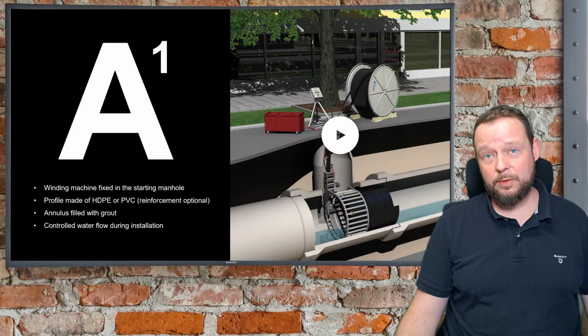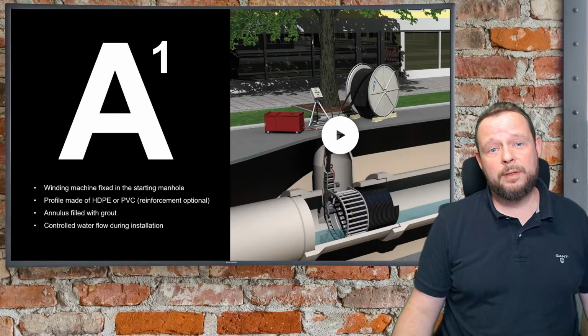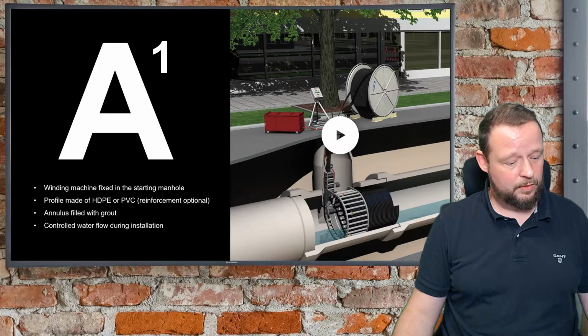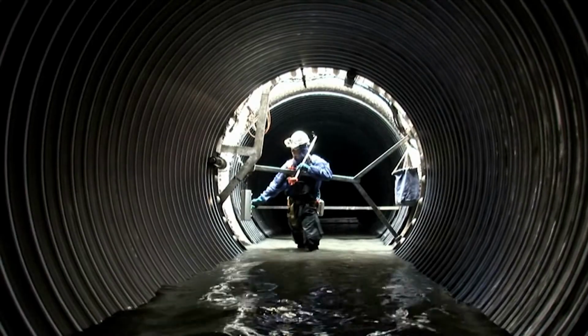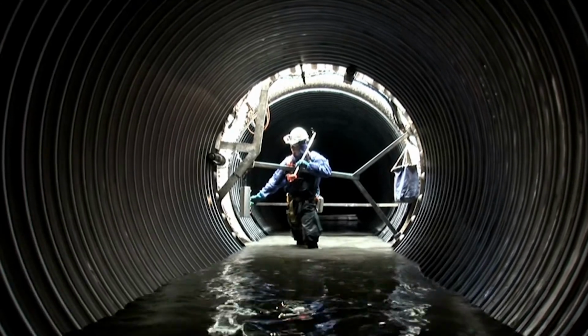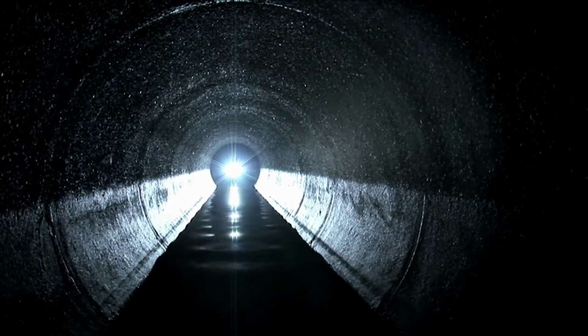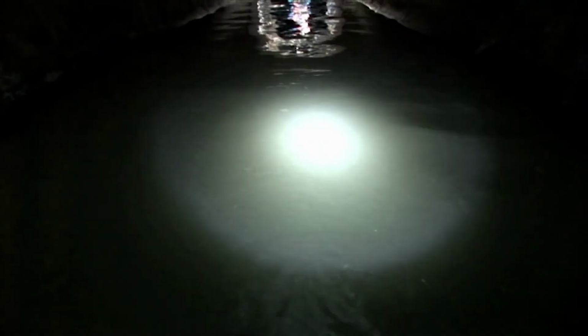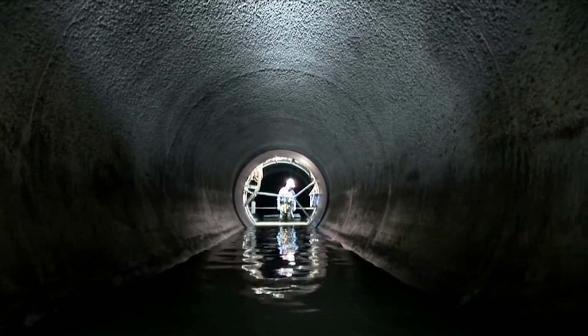So in this video you see the SPRPE technology being installed, and also some description for this. The structurally lightweight liner serves diameters from 900 to 3000 millimeters or 36 to 120 inches and is suitable for gravity flow sanitary sewer and stormwater pipelines.